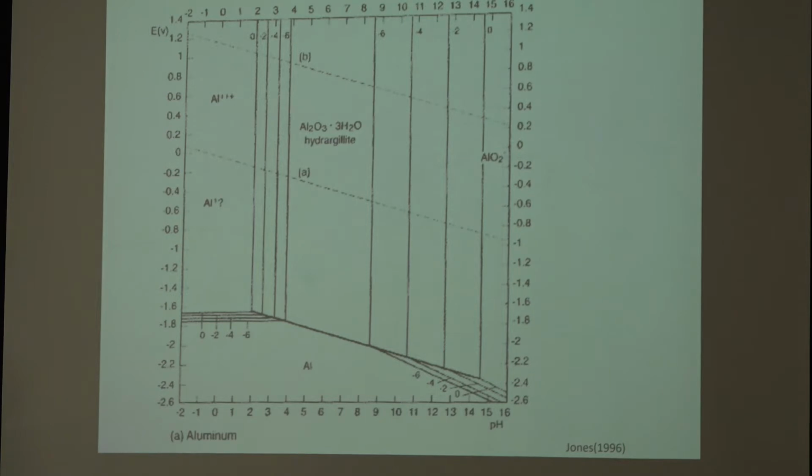Simply put, you don't have a problem with aluminum because you use it in ambient conditions where pH is around 7, maybe up to 9 for certain waters. But it's really when you fall outside of that region that all of a sudden things corrode fast.